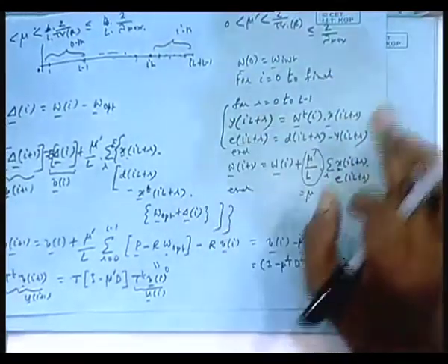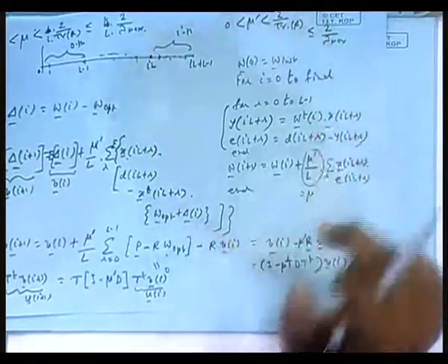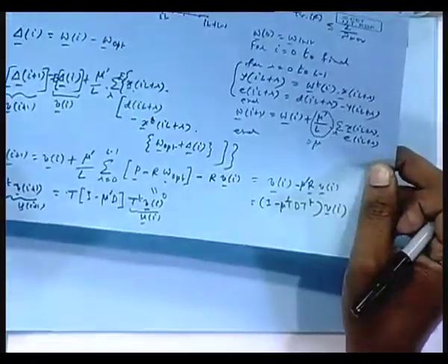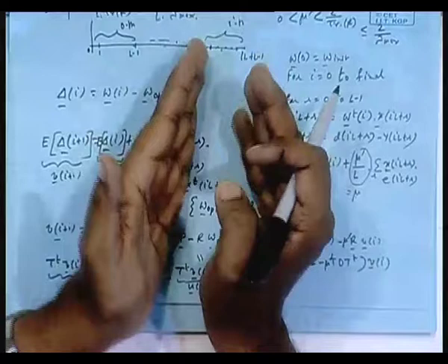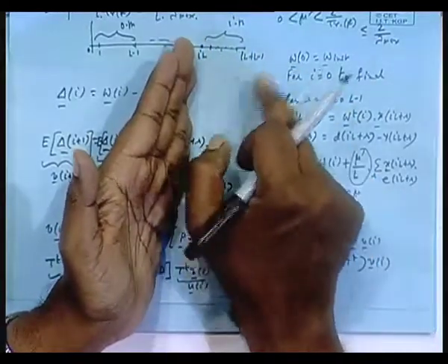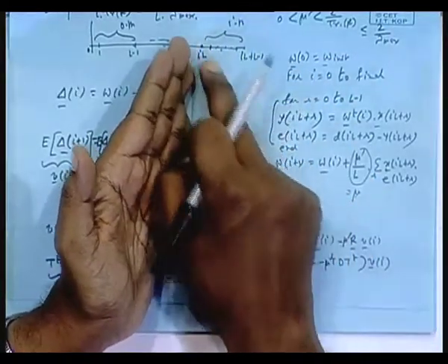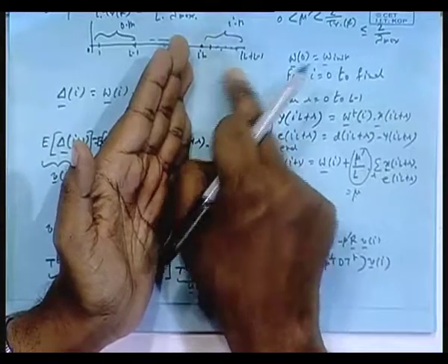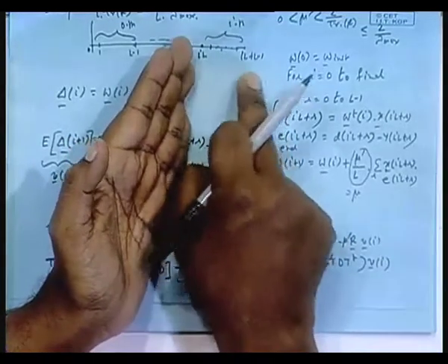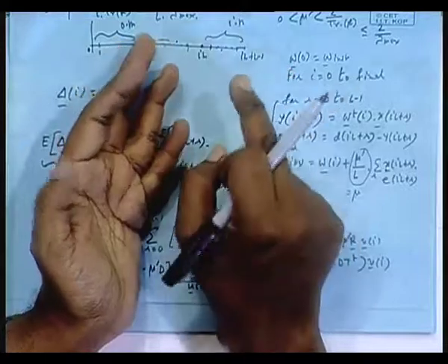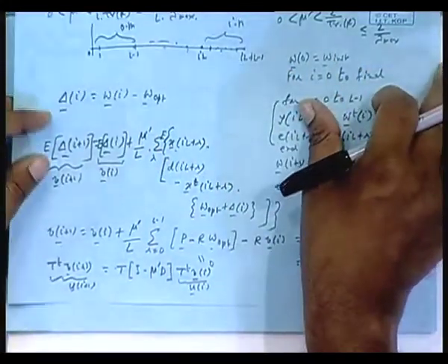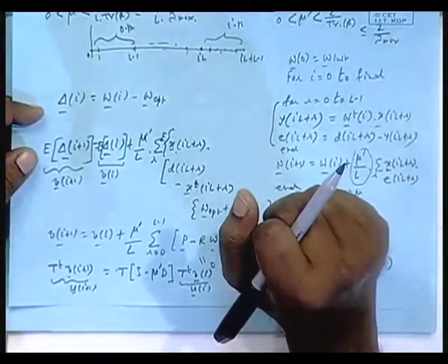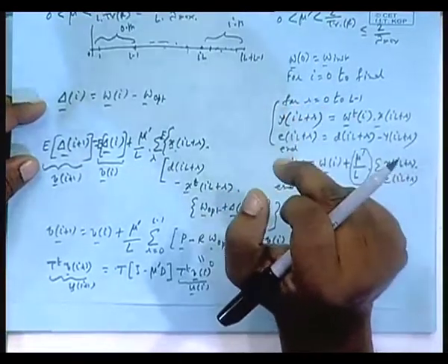Okay. So, now I am interested in the implementation of this. That is why this algorithm is so important, one full block output and weight update for that block can be carried out for all the indices, filter output, error output and weight update. All these things for the entire block can be carried out much faster than in an LMS algorithm, using FFT and all. So, now we have to get into implementation.